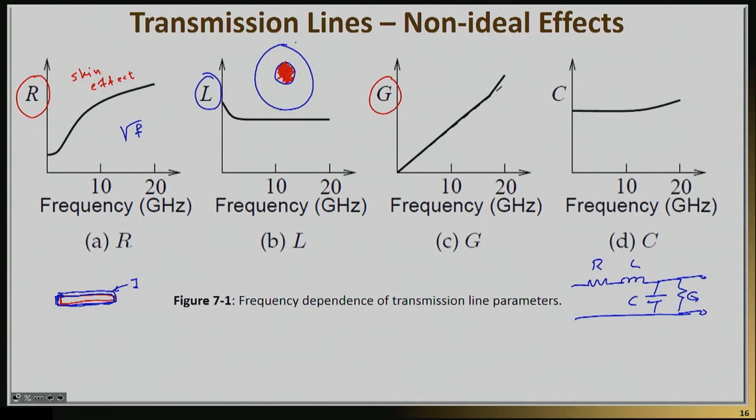Now I don't. And so that means the inductance will actually become lower. Similarly, the capacitance per unit length has a weak dependence because the dielectric of the medium, epsilon r, also changes with frequency as well. So lots of things can go wrong as you imagine shifting things over frequency. And that's, by the way, one of the reasons why wideband circuits are actually harder than narrowband circuits.